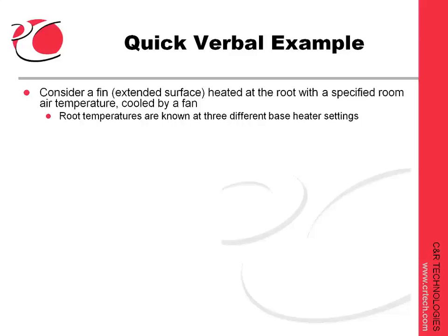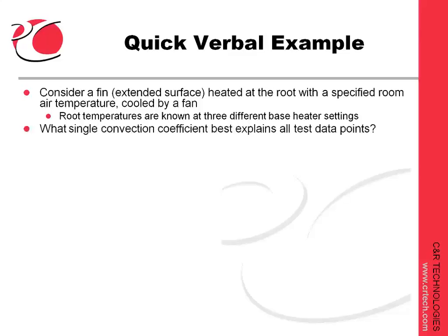In fact, this example is derived from the same problem used in the solver introductory video, a fin or extended heat transfer surface. But this time, instead of adjusting dimensions to get the lightest weight fin, let's leave the dimensions fixed. This time, we're admitting that we really don't know the convection or film coefficient between the fin and the environment. To narrow it down, we've run 3 tests using 3 different power settings for the heater at the fin's base. We then measure the temperature of the fin at one point during each of those tests.